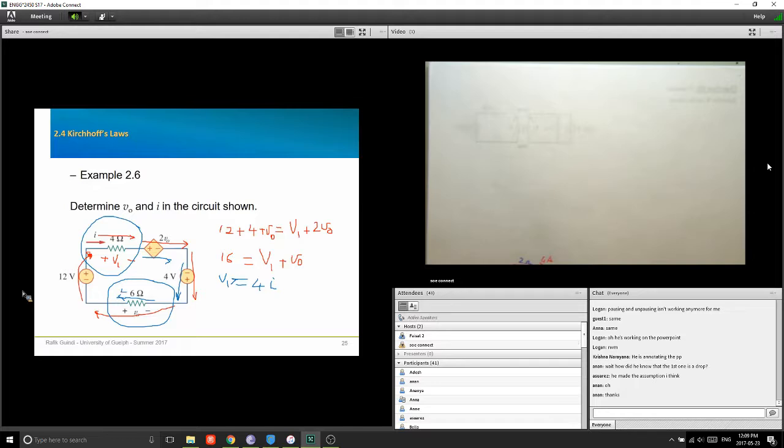That's current I. So I can write another KVL equation down there. But now be careful. The current I and the voltage V0 that are put here are not according to the passive sign convention, and that's important for Ohm's law. Ohm's law always says that the current in your resistor has to flow from the higher voltage to the lower voltage. So I have to be careful: it's like I have a voltage plus here and minus here, and I have negative V0. And I have the plus and minus in the same direction of the drop for the current.